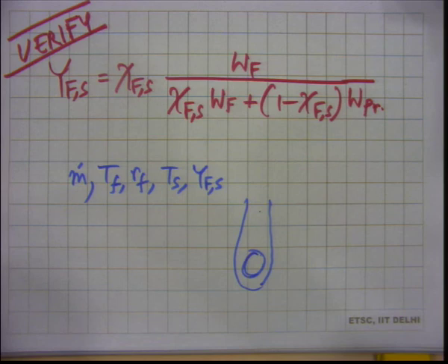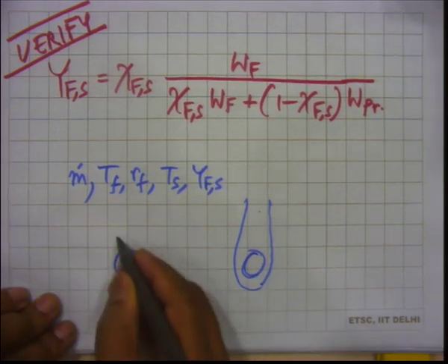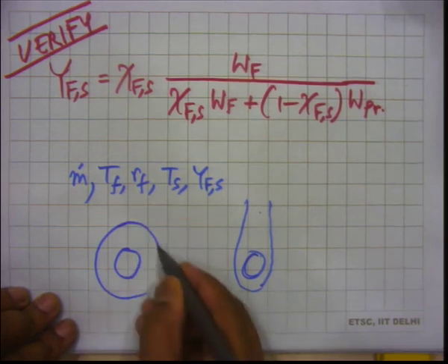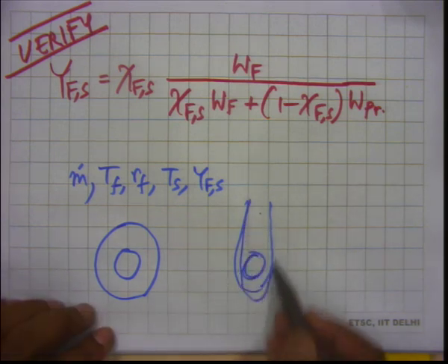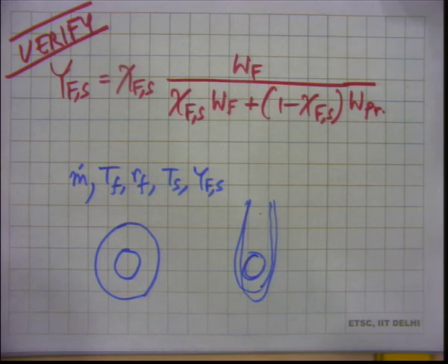Okay? So our flame is actually not like this. Our flame is, you have the droplet and you have a flame around it, which is easier to study because this is then just a spherical coordinate where variations are in the radial direction. So all equations had only d/dr, wasn't it? There was nothing else. Because if you get a shape like this, there is buoyant flow, and it becomes more complicated.